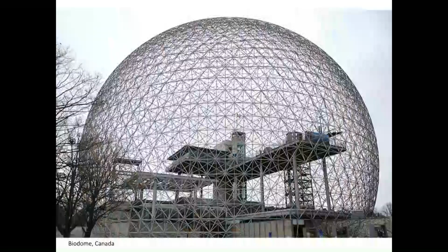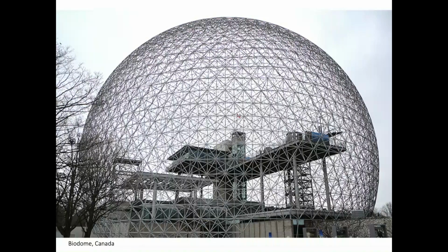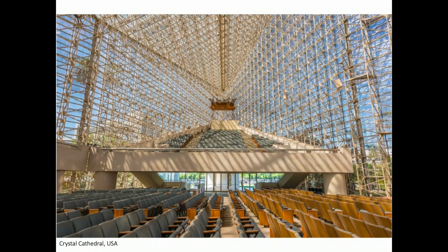And we will be particularly looking at space frame structures, trusses. So they comprise of members, sticks, which you combine with joints. And these structures became very popular after the 50s, when Mero, a German constructor, patented a system that allowed you to have a joint in which you drill holes and then you connect members, and it was very easy to build quickly and large-scale structures. So people started using them in large span applications.